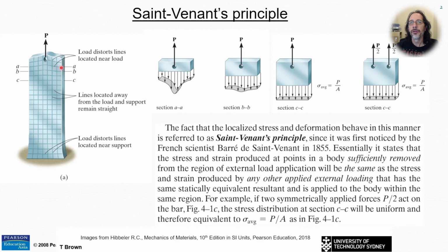Through section AA, if we look at the stress distribution, it's fairly intuitive that the stress is going to be higher near where the load is applied and less out towards the edges. But as we move away from where the load's applied, we'll see that these stresses begin to become more uniform.